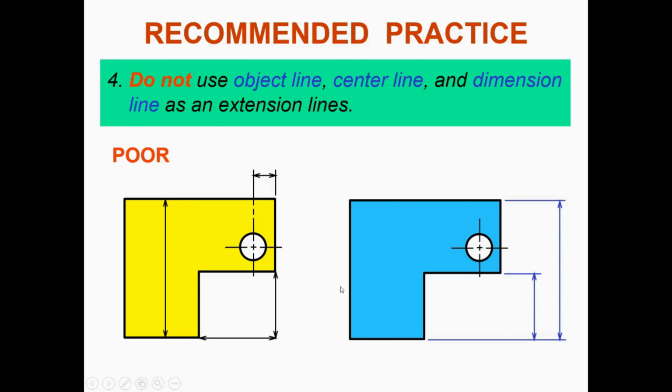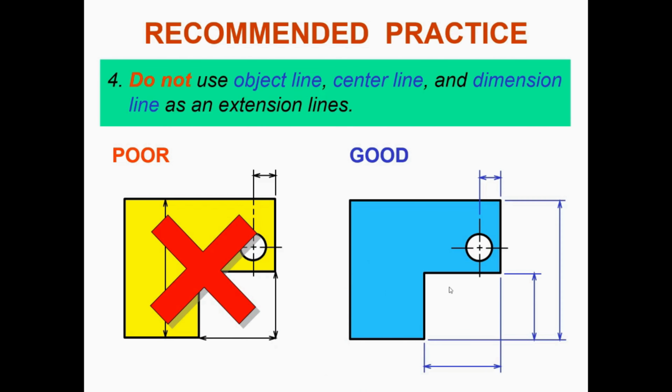You're not supposed to use the center line and the dimension line as extension lines. So again, this is the right orientation and the right practice that you are supposed to adopt.